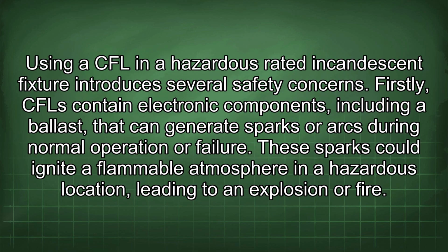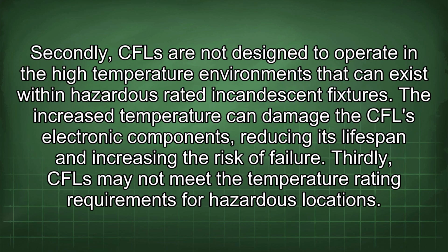Using a CFL in a hazardous rated incandescent fixture introduces several safety concerns. Firstly, CFLs contain electronic components, including a ballast that can generate sparks or arcs during normal operation or failure. These sparks could ignite a flammable atmosphere in a hazardous location, leading to an explosion or fire. Secondly, CFLs are not designed to operate in the high-temperature environments that can exist within hazardous-rated incandescent fixtures. The increased temperature can damage the CFL electronic components, reducing its lifespan and increasing the risk of failure.